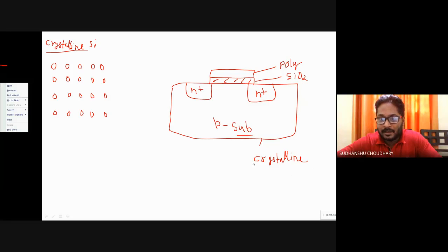As I said, we don't have any separate material called poly or polysilicon. It is the same material, silicon, but it is called polycrystal. Why? Because you see the silicon dioxide here, right? This is not in solid form. This is in an amorphous state, or maybe gaseous state. Now on this amorphous silicon dioxide, you deposit silicon. Not polysilicon. There is no material in this world called polysilicon. So you're depositing crystalline silicon on this amorphous silicon dioxide base.